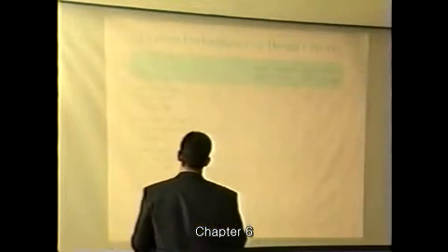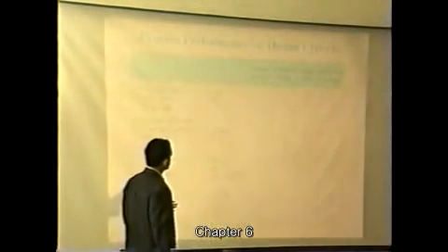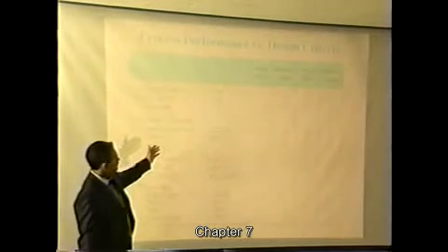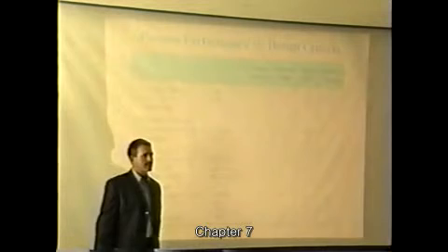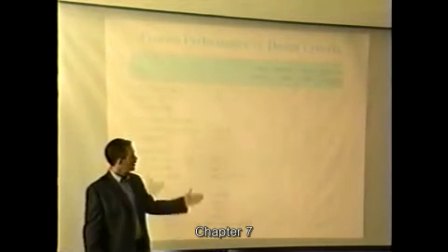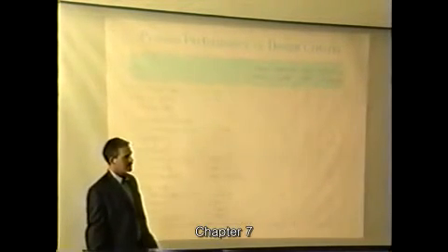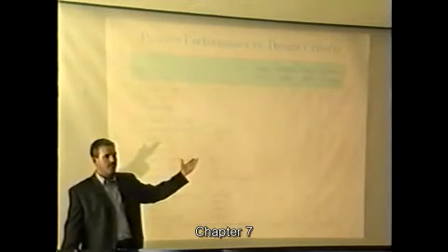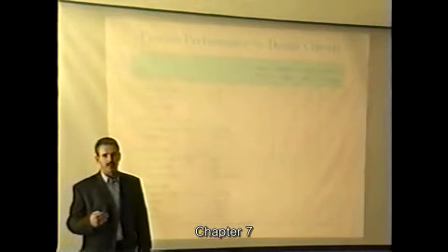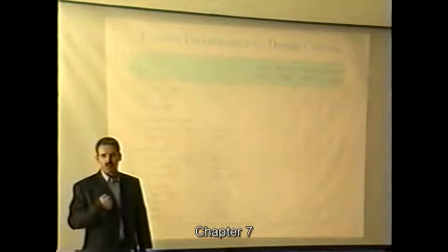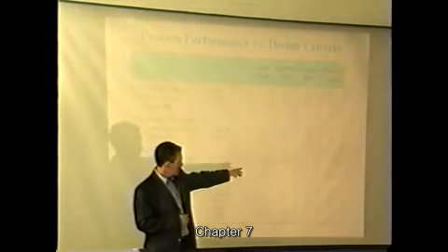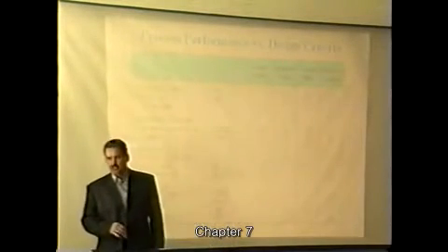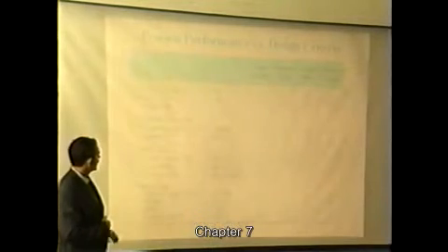If you're looking at, it's not very visible unfortunately, activated sludge systems we've discussed. The plant is designed for about 15 megaliters a day. It takes 20 megaliters a day. And at 15 megaliters it was not able to remove any ammonia. At 20 megaliters, we're converting the ammonia by at least 50%, from 21 down to 7. It's actually more, 60-70%. The same on the trickling filters,